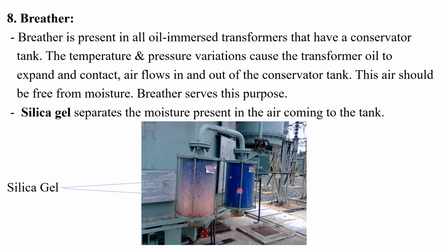Normally, the pure color of silica gel must be blue. If it absorbs moisture after a long time, the color of this blue or pure silica gel becomes pink colored silica gel. At that time, we must understand that it is necessary to replace this silica gel.